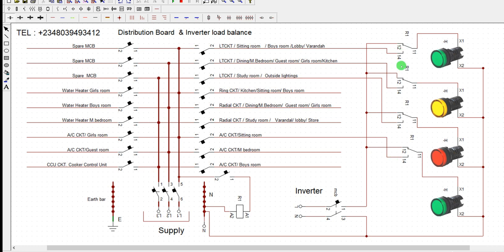Supposing I use 3 circuits only, I didn't use the power circuit, and this is just 5 amps coming from here, I would have used 10 amps here. The relay contact should be 10 amps rather. But because I use one relay that will include the power circuit and also the lighting circuit, I now use the AC to size the relay. I use the AC power to size the relay. Okay, see the reason why I use 15 amps here. All right. Okay, so thank you.